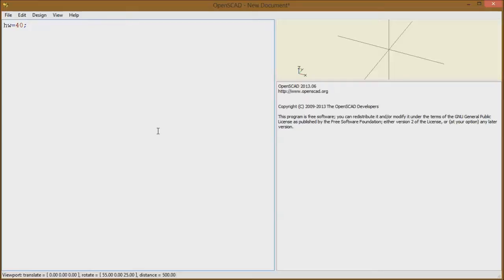However, in most of your slicer software, you will specify a unit to be a millimeter or whatever you require. So we're going with units. So we'll say that height width is 40. The depth of the piece is going to be 20. So this represents a bracket that is 40 millimeters by 40 millimeters, and it'll be 20 millimeters wide. So you'll be able to attach two longer pieces of, say, 20 millimeter extruded aluminum together.